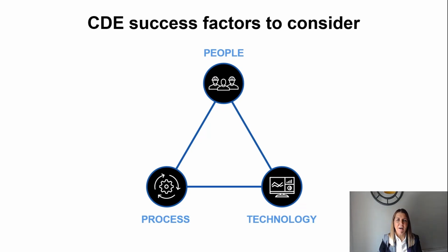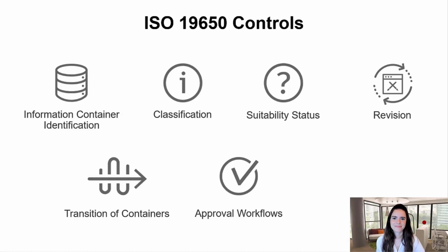And functional. ISO 19650 has some basic requirements for a CDE. Containers to be uniquely identified and supported by metadata with at least revision code and status code. So being able to check when uploading is helpful to ensure information conforms to the naming standard and associated metadata.